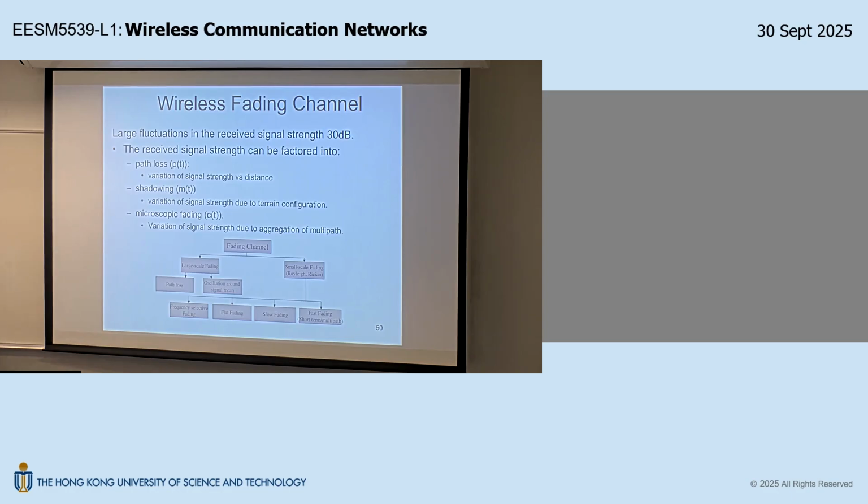So in this example, the so-called channel model of the coaxial cable is encapsulated by this channel response, or the impulse response. Is that okay? If you buy a different coaxial cable, each coaxial cable will have its own impulse response. So when you buy a coaxial cable, you just need to ask for the impulse response. That's all you need to know, because that completely encapsulates the physics of the coaxial cable. Is that okay?